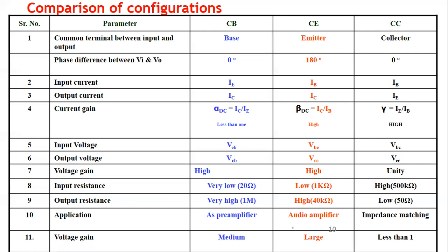Good. So that is very important, right? The voltage gain that we are seeing for common base is nearly equal to 1, 0.99 or 0.95, nearly equal to 1. But in the case of common emitter, it is more than 1, 20 or 20 to 50, or we can adjust it by whatever components are there. And in the case of common collector, of course it is the reverse, so it has a gain of less than 1. So this is what we have to remember, right?